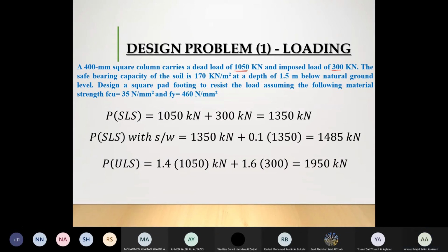Now, if I go and add extra loads, which act as the loads of the columns, you will see that my paper is going to start bending. That's the main reason why we don't take the self-weight of the foundation into account when it comes to bending moment. When we calculate bending moment, your foundation acts like a paper.